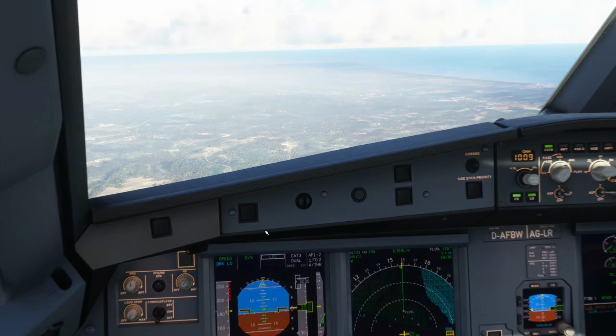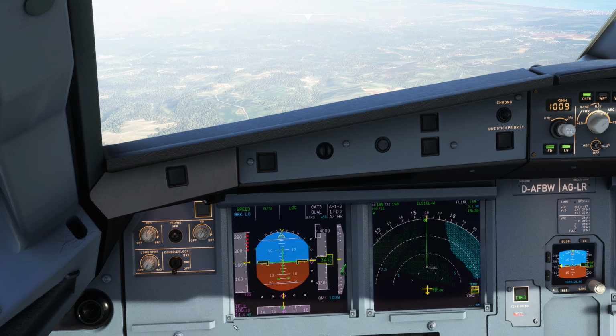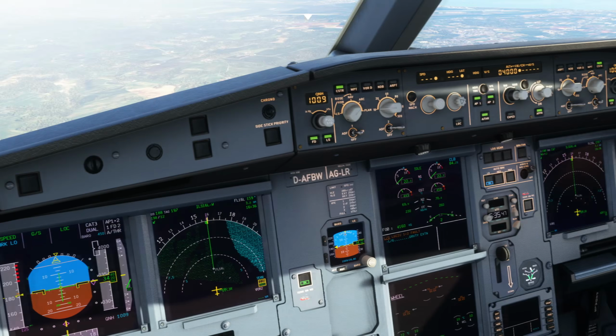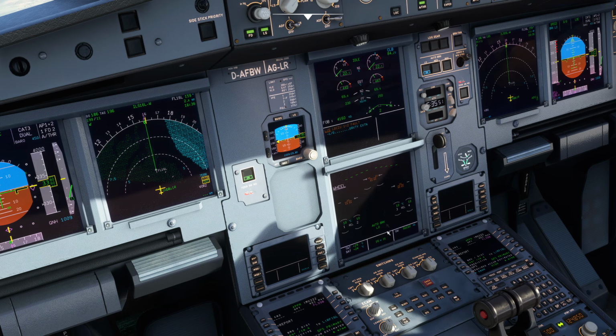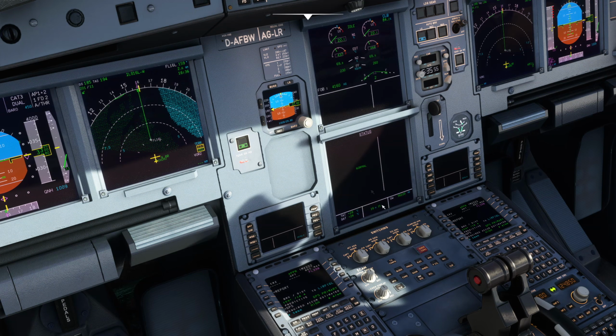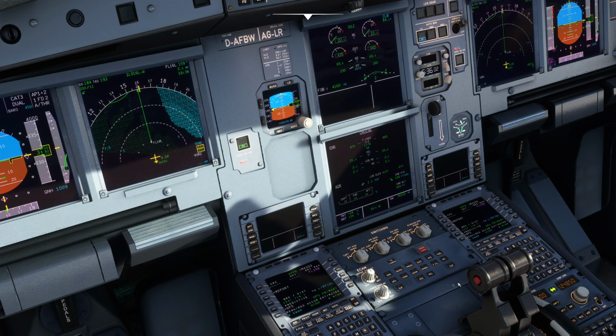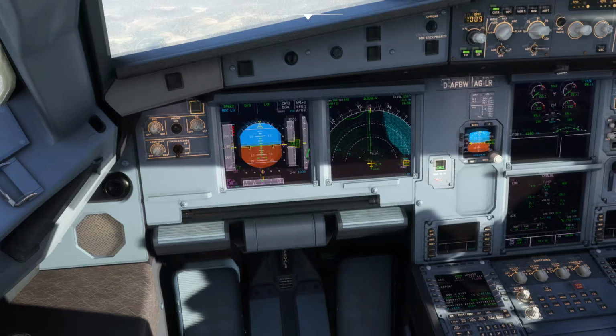Okay, so here we are now on final approach on the ILS for 16 left at Rome. As you can see, we're about 11 nautical miles out, doing 180 knots. I've just put out flap 2. Our ECAM is still here, asking us for landing gear gravity extension. Of note in the real aircraft, if you cleared away that ECAM, it would then tell you on the status page as well, landing gear gravity extension. But anyway, things are obviously not normal, but that's not a feature implemented yet. But still, great to see these ECAMs starting to come through. That's a big part of flying the Airbus.